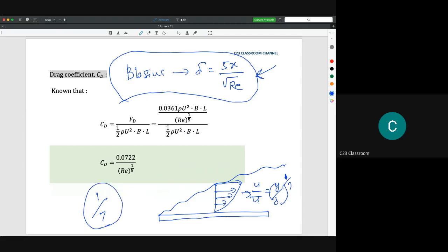turbulent boundary layer. Because normally at normal speeds, for our applications like our car and so on, it is quite suitable with the 1 over 7 condition. If more, we need a high velocity to create that Reynolds number. Later on in our discussion, I will show you about the higher Reynolds number, because the application for this is actually more about the lift force later on.